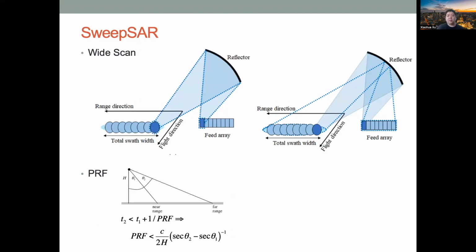There, however, is another way of expanding the acquisition area, which is to use a reflector on top of your satellite and face your antenna toward the reflector. This way, different parts of the antenna, when they are hitting the reflector, essentially arrive at different parts on the ground. You could do it similarly as the traditional approach, which lights up the ground one by one and records the returned radar echoes to form images. However, this is a waste of the potential of this design, as you are basically only using part of this antenna. Another idea is to just illuminate the whole antenna at the same time.